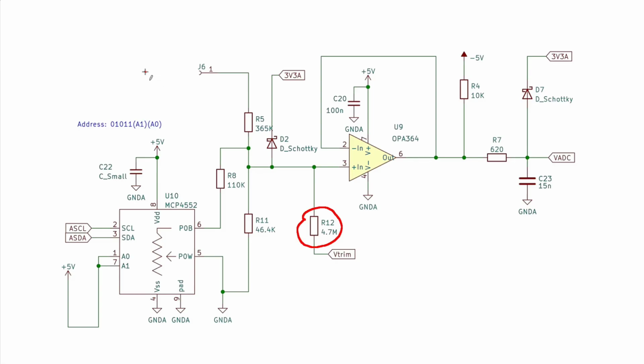With J6 shorted to ground, I get less than 1 millivolt on the VADC pin, so if I actually need to trim the offset of the op amp, I'll add that at a later time. The only filtering that is in place is the charge storage capacitor and the resistor feeding it, coming in at about a 17 kHz cutoff frequency. That is a higher cutoff frequency than I was planning.